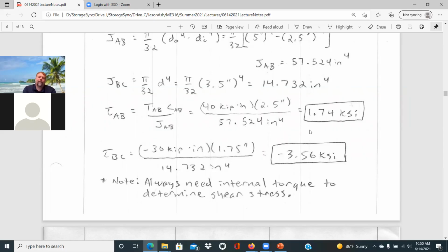The other thing you have to be careful is generally what is provided for a material strength is, say, the uniaxial yield strength. And that does not correlate directly with a shear stress. Materials fail in shear much sooner than they do in axial loading. And so that's the intent of failure theories.